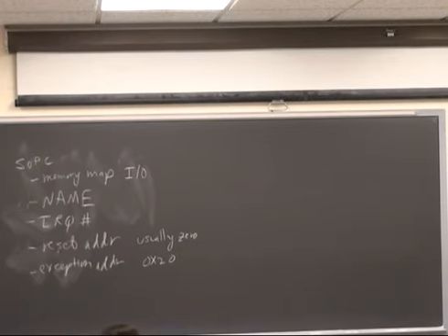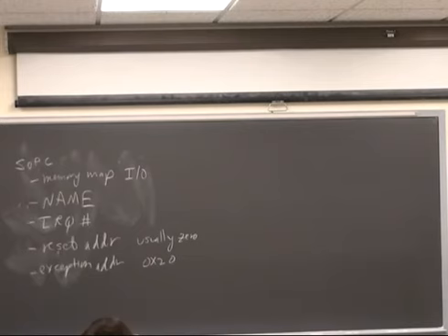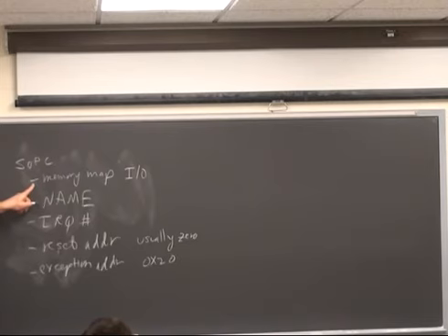If you want to, optionally in SOPC Builder, you can add instructions to the CPU. If you want to, you can add hardware to the CPU. You can write your own bus-oriented I/O using a module generator for SOPC Builder.